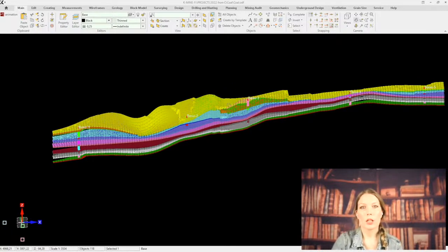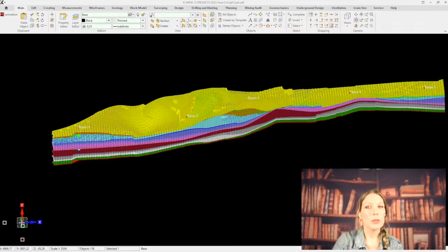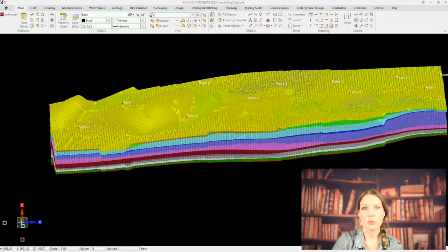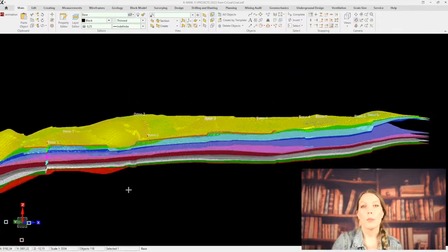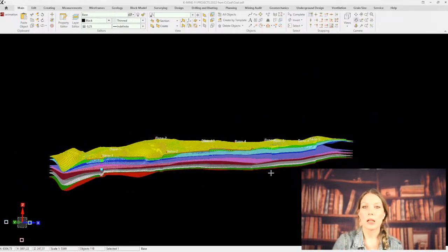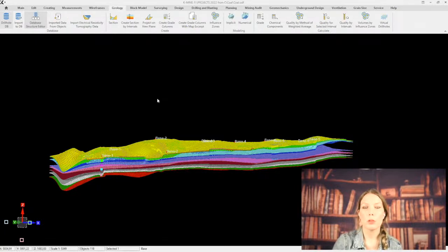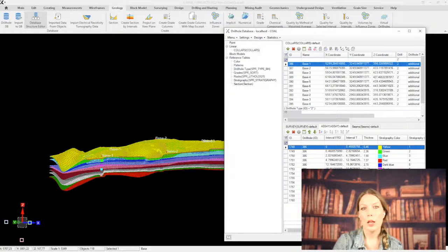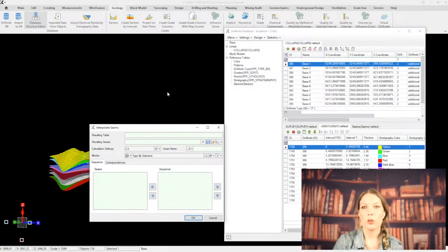And a common question that comes up is about splitting coal seams during modeling. K-Mine offers a mechanism for recalculating mother and daughter seams directly into the database. To do this, first recalculate the new table and correlate the seams before creating the seam block model. You'll need to specify the necessary reference books, the full chronological sequence of seams, and the calculation algorithm.